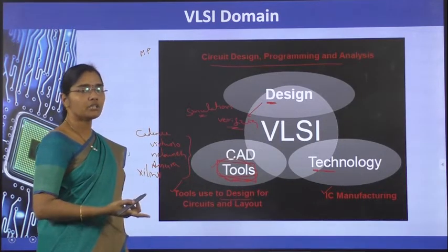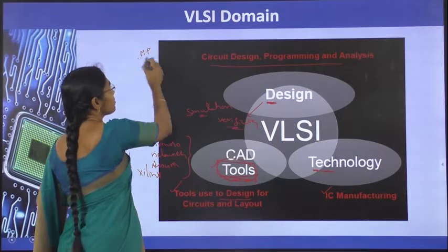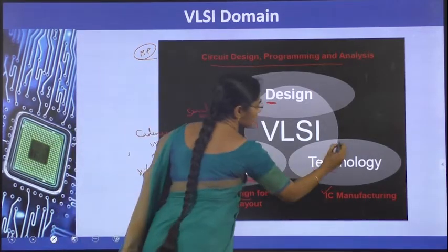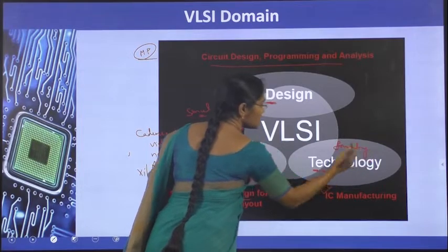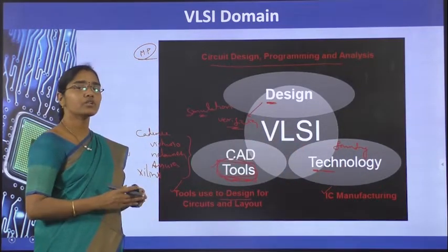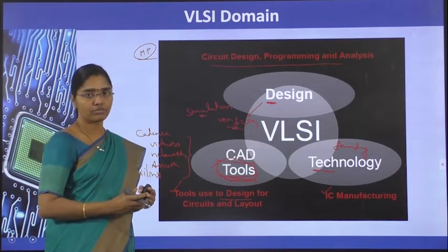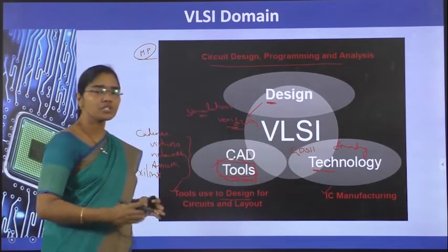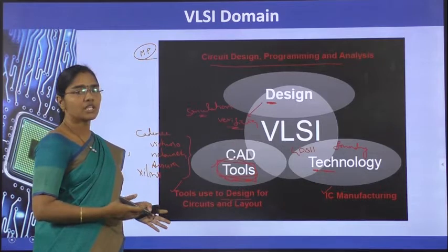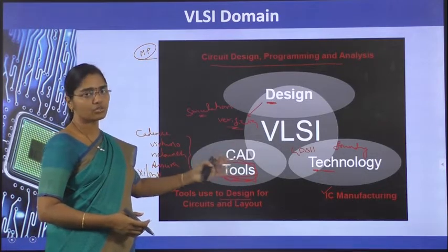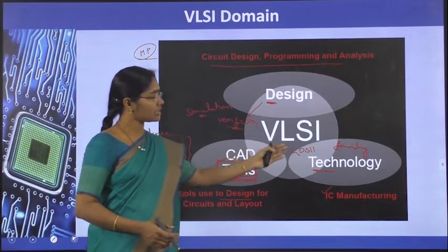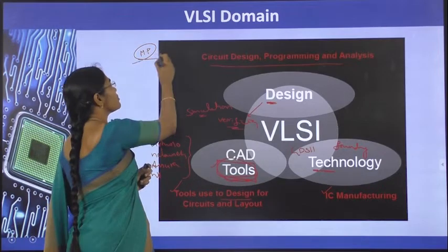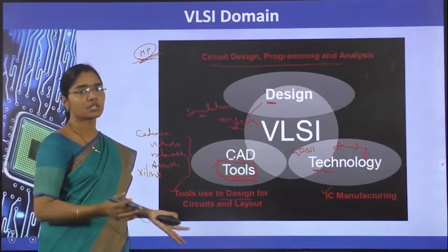Then finally what we need is a hardware chip for this microprocessor. For the hardware chip, the fabrication industry is required. So the fab industry is doing this technology part, where the IC is fabricated for the given file. That given file is in the form of a GDS2 file that was generated from the layouts. Those layouts will be generated by these CAD tools with the help of the designers. Then the IC is fabricated, and that fabricated IC will be used as an application in our circuits.